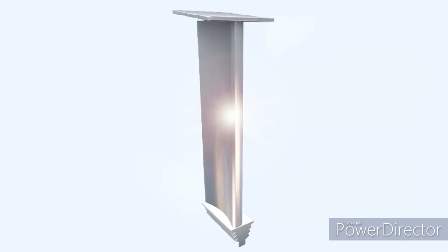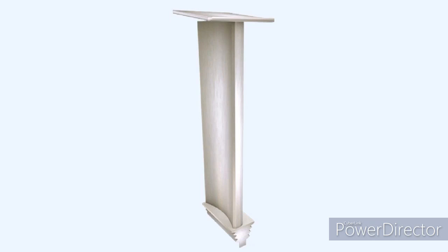This process virtually eliminates corrosion and creates an extremely creep-resistant blade. Ceramic materials are also being used in the production of turbine blades. Originally, the ceramic was applied as a plasma spray, the coating giving very good protection against a corrosive condition caused by a reaction between the base metals of the blade, the sodium in the air, and the sulfur in the fuel.